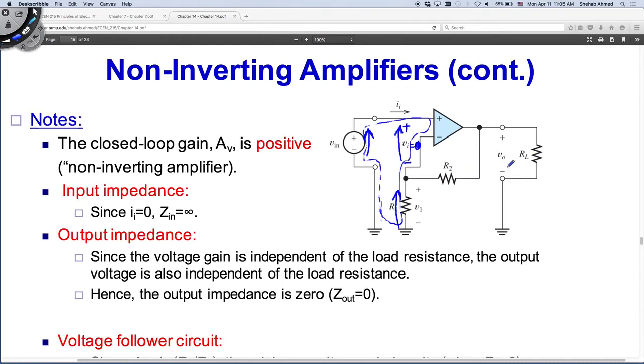And this output voltage is going to equal this voltage plus this voltage. So now I've created something else. My output is not really driven by my open loop gain anymore. It's driven by the circuit that I put around the op-amp. This is the whole objective.